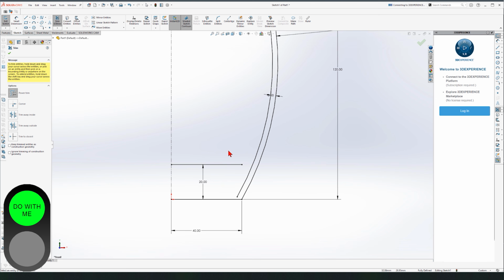The way I do this is not like that. If I do it, I just get rid of that point completely. So how do I do this? Green light, okay? Put your mouse on that line, somewhere on that line. I'm not clicking anything. And then click and hold, and then drag, drag, drag. You can go further, or you can just see this snapping effect where this line turns orange and leave it here.